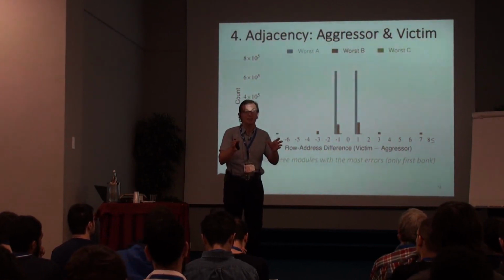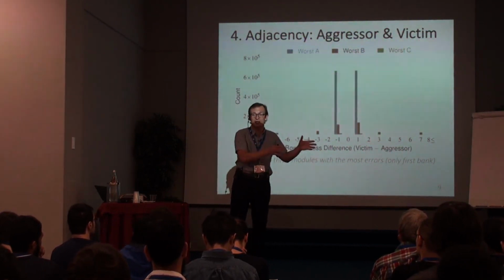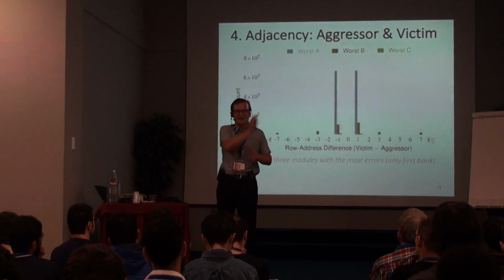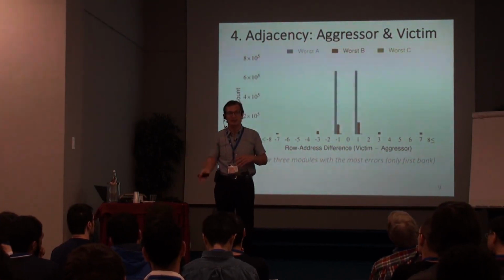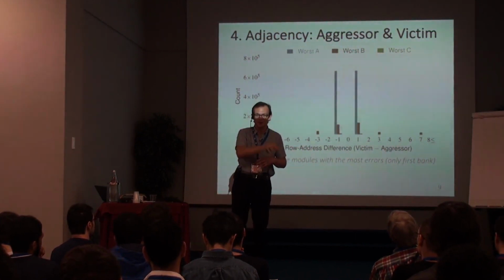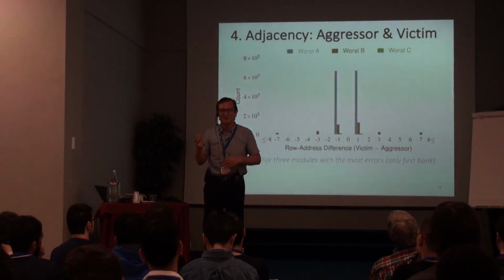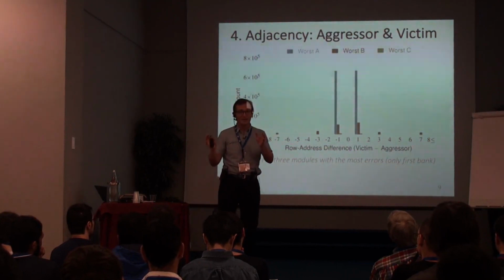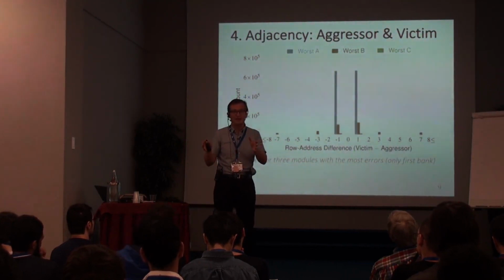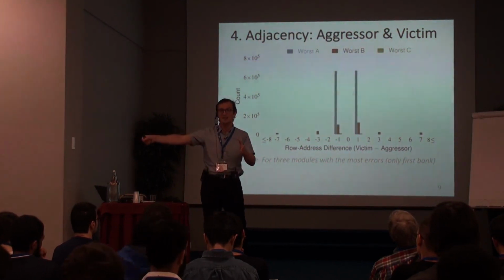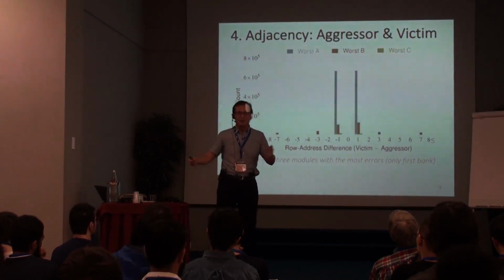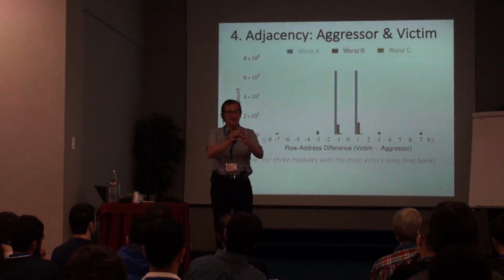Like in the past, for example, memory controllers were actually not on the processor chip, right? If you go back, I guess 15 years, AMD was the first general purpose system that put the memory controllers on chip, and Intel followed suit quickly because it was a really good idea to put the memory controller on chip. But before that, you had these memory controller chips that were manufactured separately. The processor used to access that memory controller chip, and the memory controller chip used to access memory. Now, because of integration, we're able to put many things on the same chip.